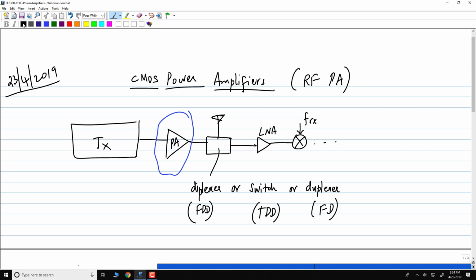If you want wireless LAN, people get together and decide that the wireless LAN standard needs to have a range of, let's say, 100 meters. If you're looking at cellular, 100 meters is just not good enough. You'll need too many base stations. It's not economically viable. So you want at least a kilometer, a couple of kilometers of range, before it'll be viable for cellular. If it is Bluetooth, it may be much smaller, like 20-30 meters and so on. So the application decides the range of the transceiver.